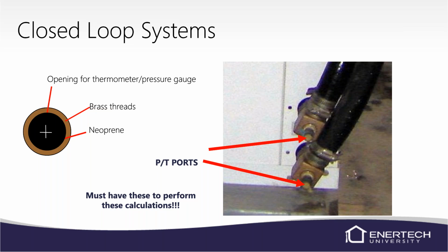And we've got to have our flow, because if we don't know our flow, the flow can affect your refrigerant pressures and how the unit operates, obviously. It's like having a condenser fan motor that's not operating on a standard AC or a heat pump. If it's not working, you can't expect the rest of the system to work. So make sure we're always installing pressure temperature ports. If you've got more than you need in there, it's not going to hurt anything. They're not causing flow issues or anything like that. So just make sure we're always installing them.